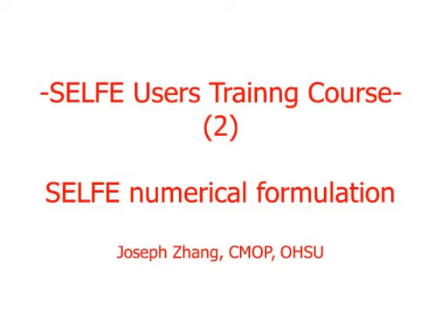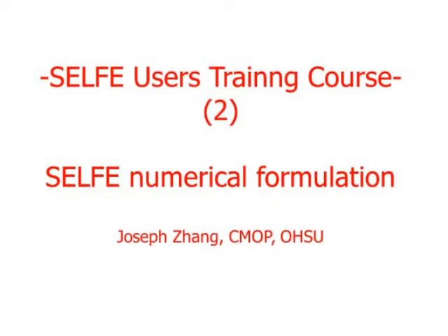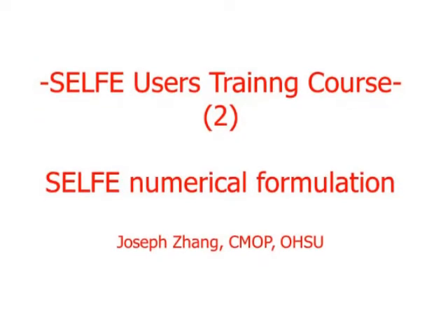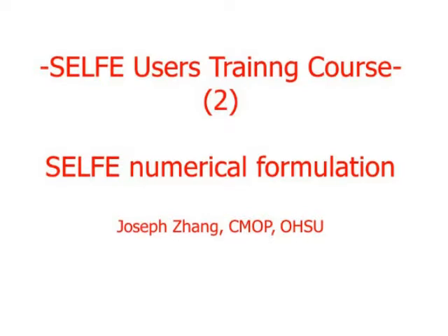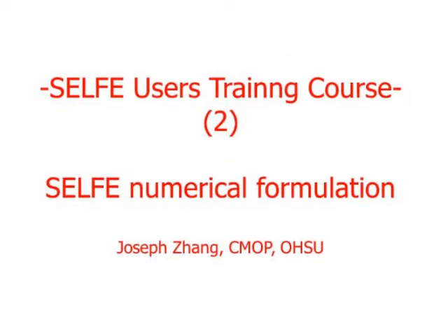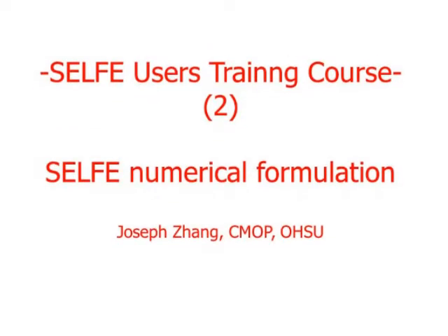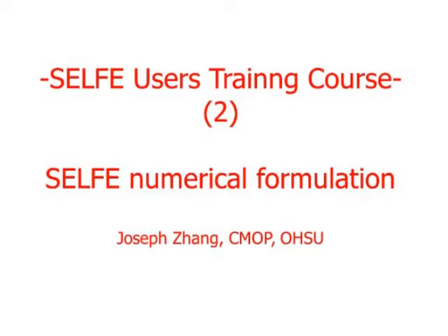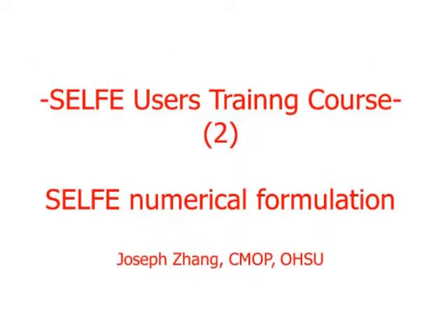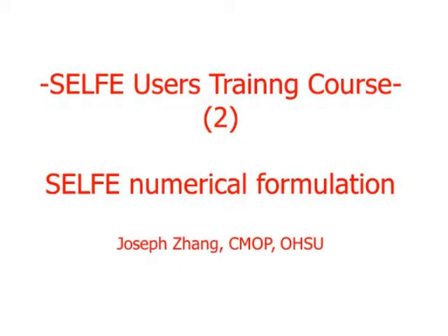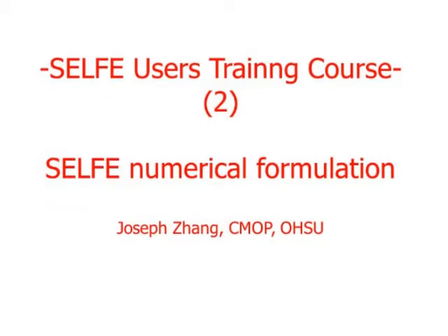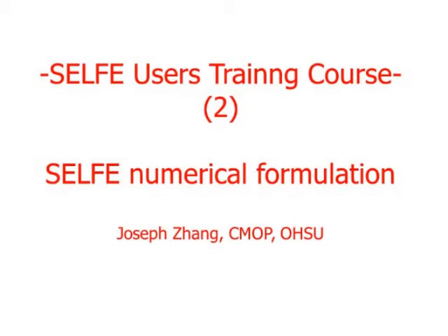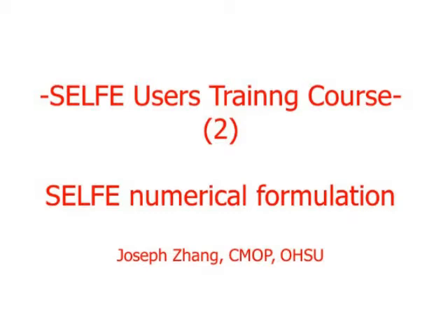So you get this horizontal viscosity term as a ratio between these two. On the top, we already used the Gauss theorem to convert the area integral into the boundary integral. So finally, you approximate this ratio by these summations. Inside here, you need to evaluate the normal derivatives of velocity at the side center.